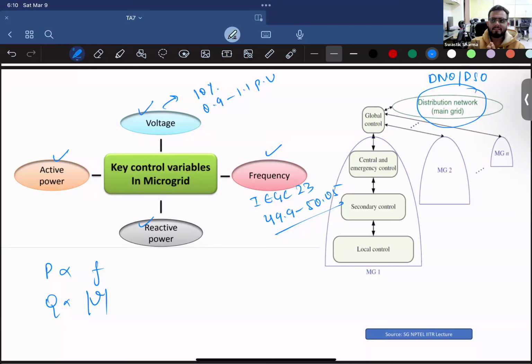Second, if we have a microgrid, we have the capability to black start. What does black start mean? Let's say our system has gone into a complete blackout, like in 2012, when there was a complete blackout of the northern grid. Black start can energize small localized areas, and these can affect a change in such a way that the whole region can be powered back. Even for powering large generating stations, we still need power, and the black start capability of a microgrid can be extremely helpful.